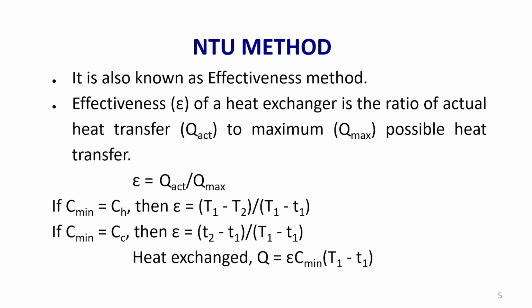So, inlet temperature is 100 degrees centigrade, capital T1. This is the hot fluid inlet. Let me emphasize again, throughout the calculations in the NTU method also we will be using capital T1 and T2 for hot fluid, small t1 and t2 for cold fluid.